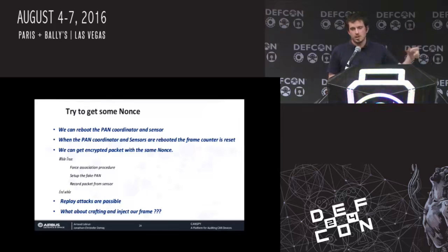We do that again and again, and we will need a lot of data, but it's wireless, so we have plenty of time to record, reset, record, and after that we do some cryptanalysis to guess the plaintext. Obviously, if you have some insight into the plaintext, it's easier. For example, if we know that we are talking about a water sensor, we can think that the value will not change really fast. And it's the kind of thing that can help in the cryptanalysis.